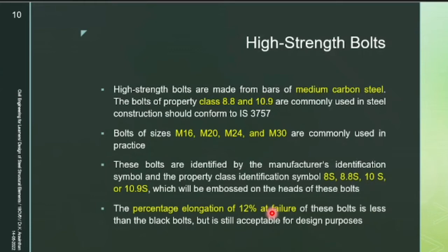This is the advantage. And in the previous class I have mentioned that if you want your bolt to fail by brittle or by ductile, your bolt should only fail by brittle. Sudden failure should come. It should not elongate. If it is elongating, if it is ductile, then the property or purpose of the bolt will not be fulfilled.